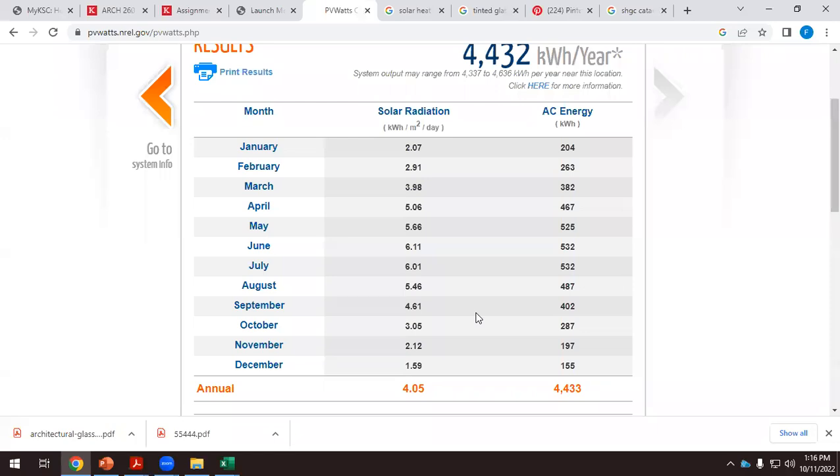So nature is helping architects, because what we need in winter is to make the most of the sun. In winter, we have vertical windows, and we have a lot of sun entering the building. In summer, with vertical windows, the sun is very high, so the amount of sun entering the building is less. And that's what we want. We don't want sun inside the building in summer. We want sun inside the building in winter. So be aware of that.